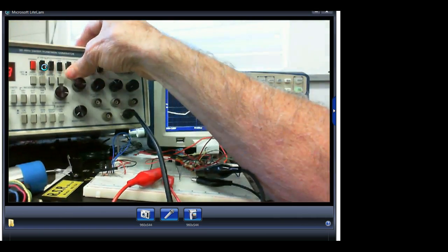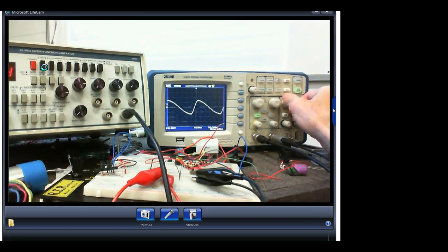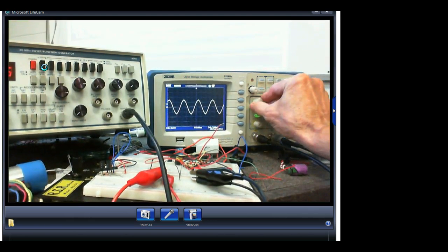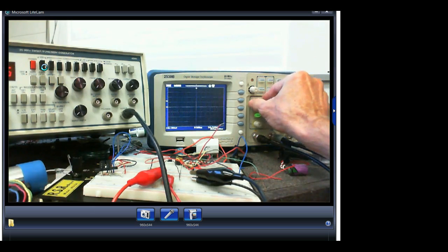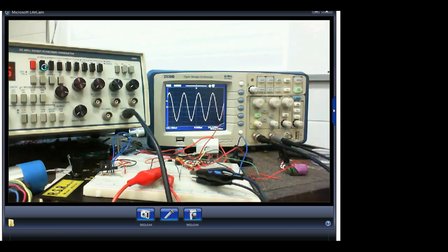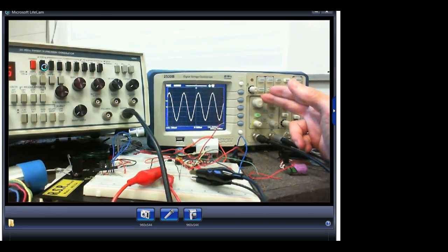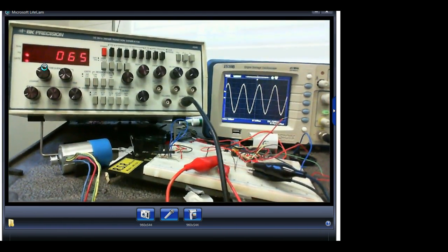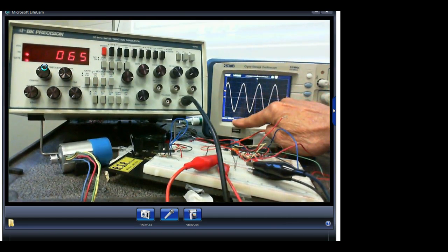Let me take off the garbage. It looks like it's got a DC offset. Oh, yeah. So there's my sine wave coming in. Now your ultimate goal is to get it as big as you possibly can on your scope and still see it on the screen. And I'm using a control called volts per division. So now we can measure. I've got it set so we can measure it pretty easy. So we got it on 500 millivolts per division.